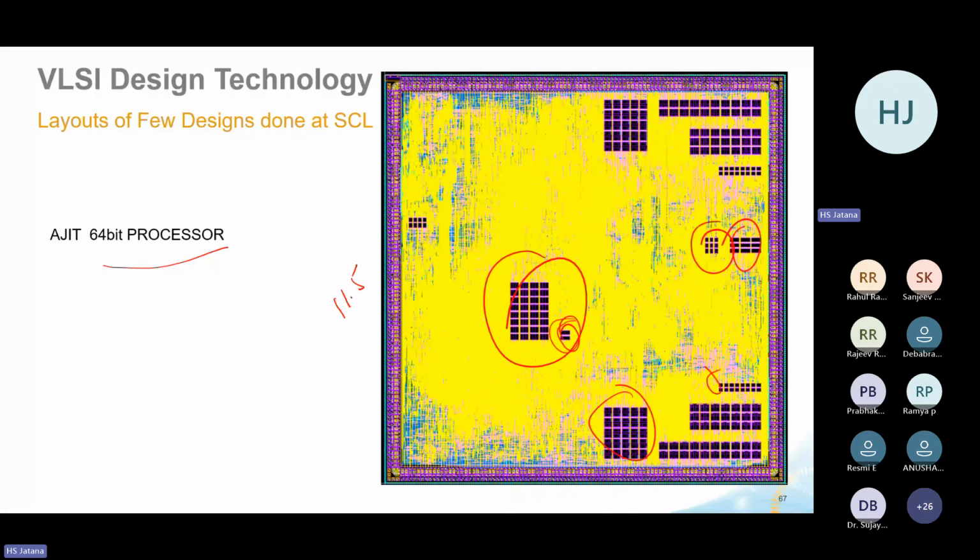Placement of these memory cuts in the floor plan will decide the actual performance of the circuit. Why is this memory placed here? Because the logic in the neighborhood is addressing these memories. To improve the functionality, you put these memory cuts close to the logic which needs that kind of scratch memory, and it's an SRAM which is being used as a scratch memory.